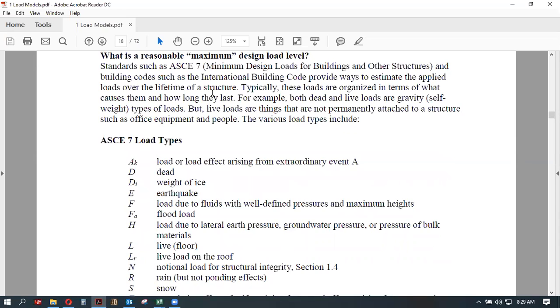Every 3 years, the next one actually for ASCE 7, for some reason they missed the 2019 cycle, and the next one will be 2022 for ASCE 7. That has to get done before you then produce the next IBC. So there's always this staggered kind of thing going on in terms of the dates. And you'll often find that, especially a small municipality, they won't be using anywhere close to the most recent version. They may be 10 years behind, which may or may not be an important thing. It just depends on what happened in the last 10 years of the changes that were made in the building code.